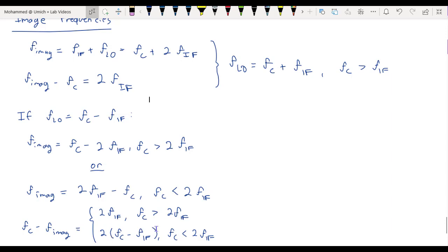And this is why we need the tunable RLC front-end filter in order to reject or attenuate the signals in the image band. And in physical AM radios, both the local oscillator frequency and the resonant frequency of the RLC bandpass filter are synchronized together when a station is selected.